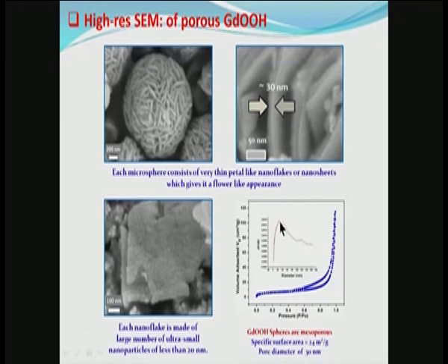What we see here is that the pore diameter has a peak at about 30 nanometers. So, this is a mesoporous sample with a significant number of pores measuring on the order of about 10 nanometers. You can see that corresponds to the SEM image quite well.